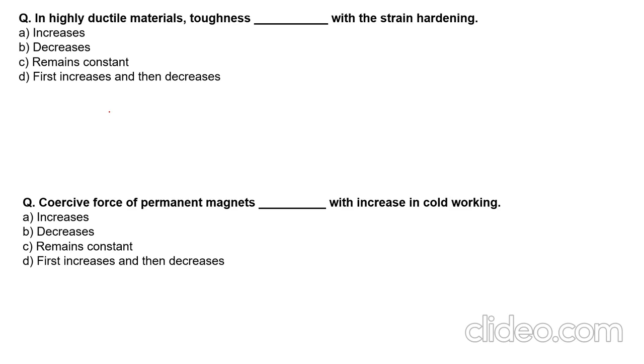Increases. It is fine, but see, for example, if you have sigma and this curve, which is a stress strain curve. For a ductile material, your curve will look something like this, right? Because it is a ductile material, it will undergo plastic deformation, but it will have a larger elongation. You can have more elongation in such materials as compared to any other material.